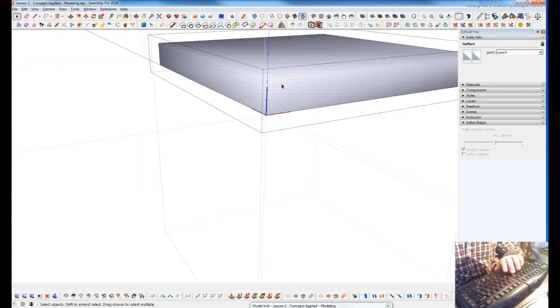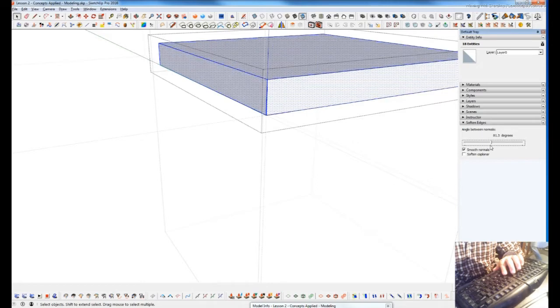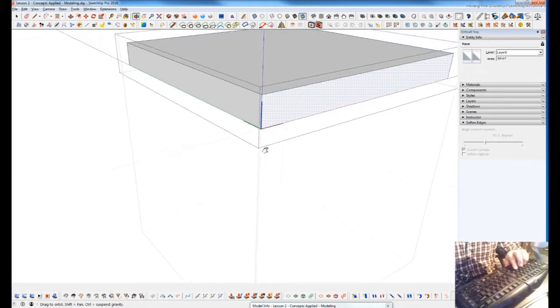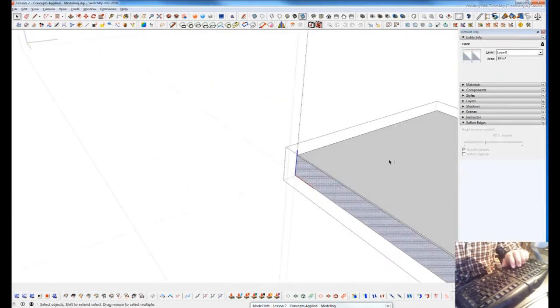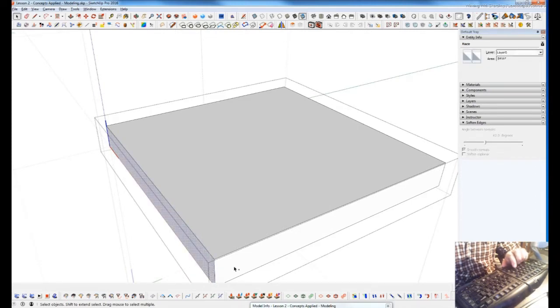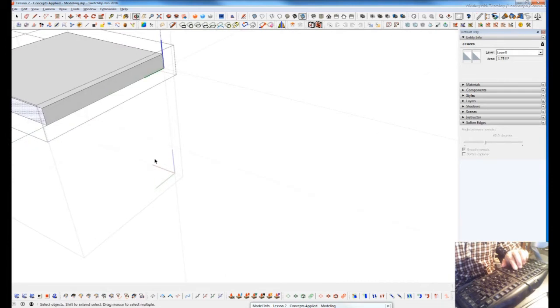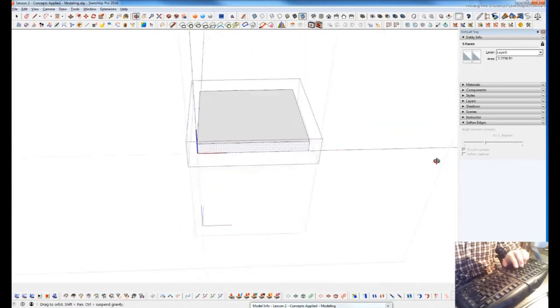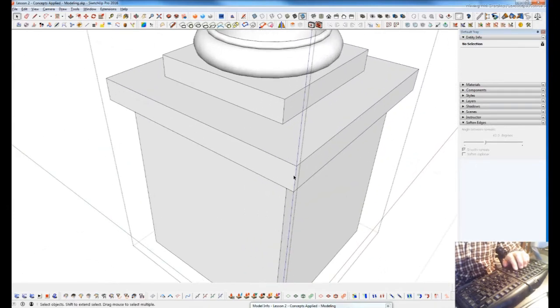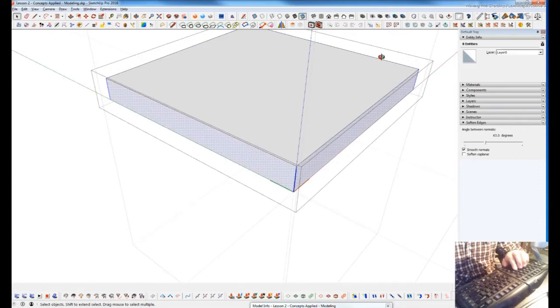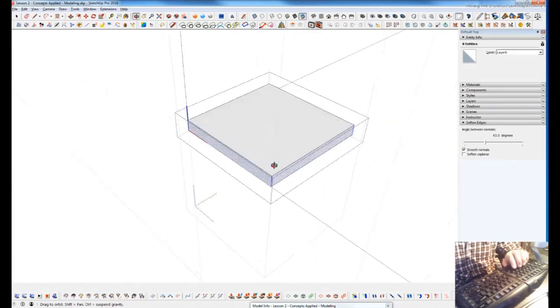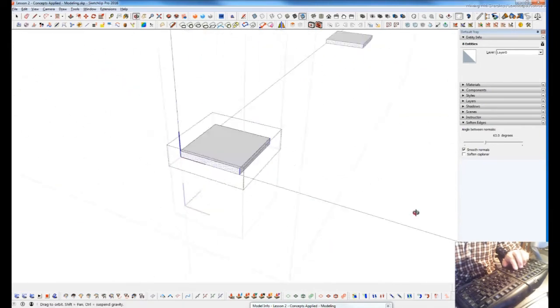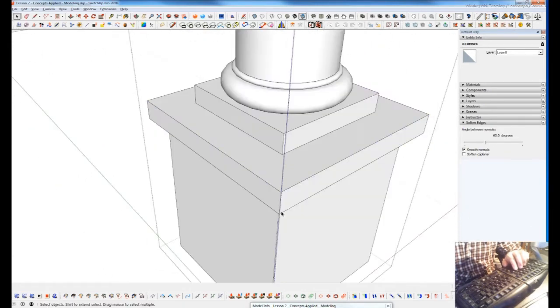But if it's set below, turn back on hidden geometry or triple click and drop that back down below 90 degrees, then those edges will harden again. But the only way in the past was for me to select all the way around, manually turn this, hold Shift, select here, or hold Control or Shift and select those other edges or those faces, and keep having to rotate. And that takes a while to get around, as opposed to being able to get inside, grab one edge, go Shift Q, and now I've selected all of those all the way around with just one operation.